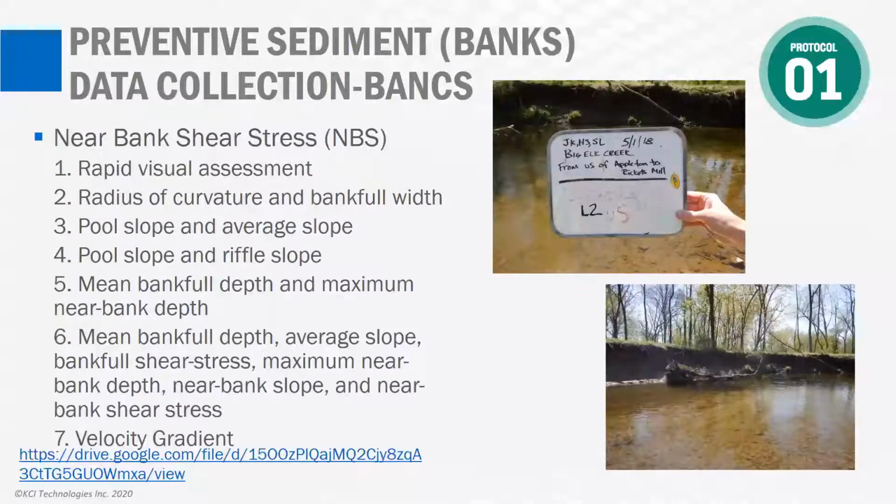So it's also important to remember photo documentation for BHI assessments. It's especially helpful to include a survey rod in the photo. It helps really add scale. And it's really helpful if you ever need to go back and reference any of your banks. The link shown here is for the bank spreadsheet created by U.S. Fish and Wildlife Service and EPR.